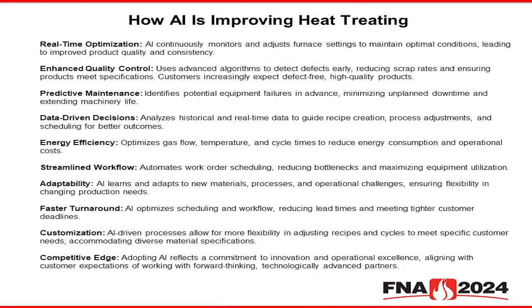Predictive maintenance or preventative maintenance, a lot of that is traditionally the ability to go through and make sure you are checking everything in time. But as data is now able to be digitized and no longer just tracked on paper, you start to be able to pick up things that normally you wouldn't see for potential equipment failure before it happens and before you get downtime. So that's a big one. There are a lot of solutions on the market for this. There's also the ability to integrate that into a bigger picture, which I'll talk about in a minute, to make it even more advanced.